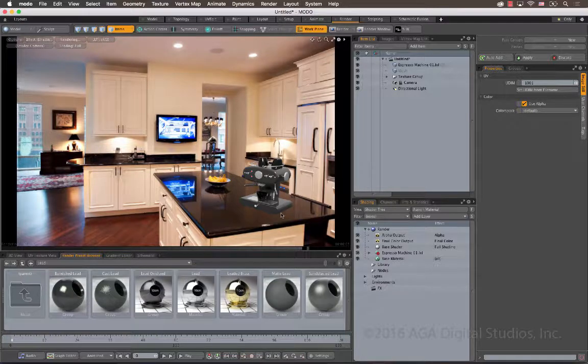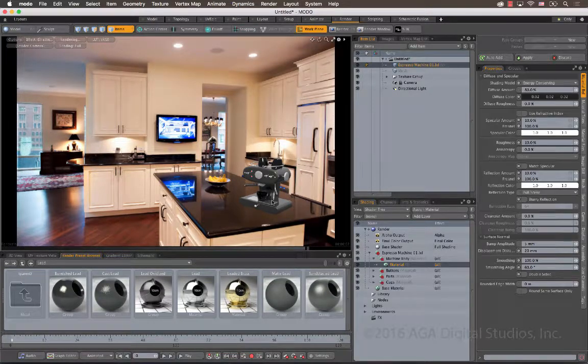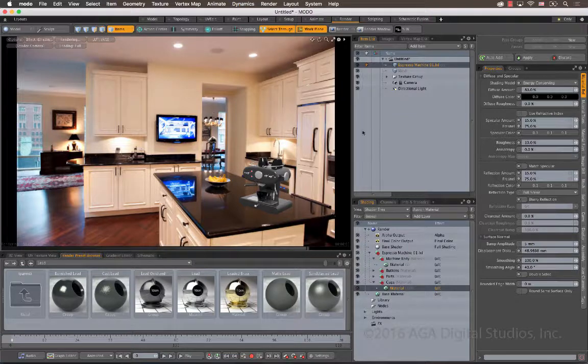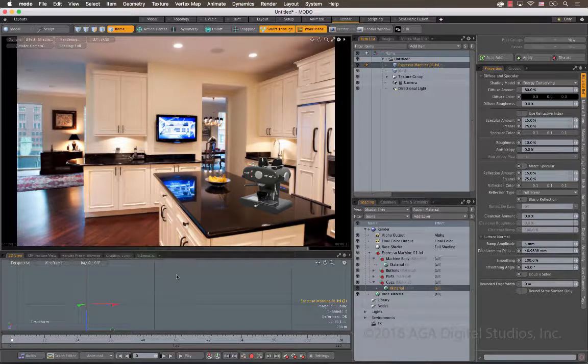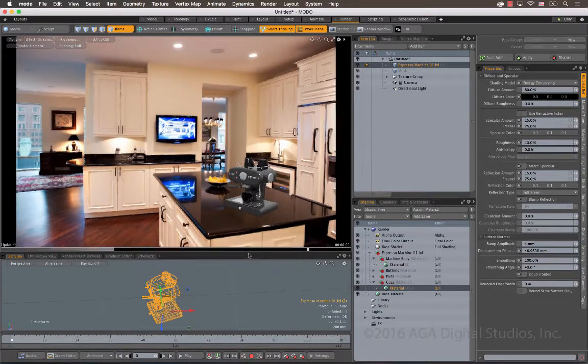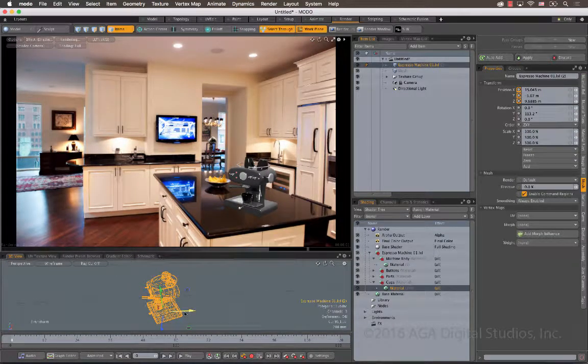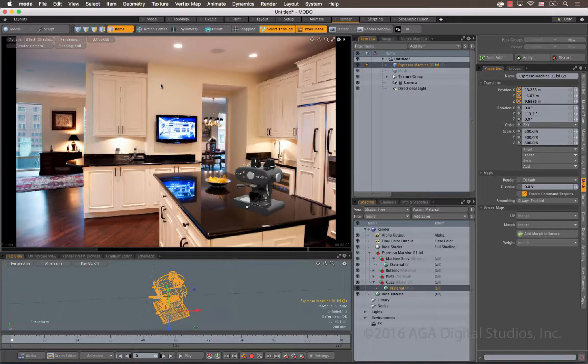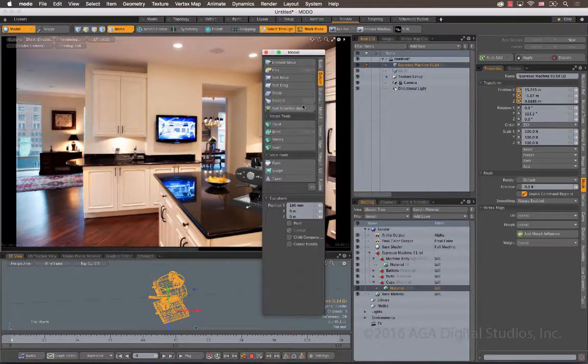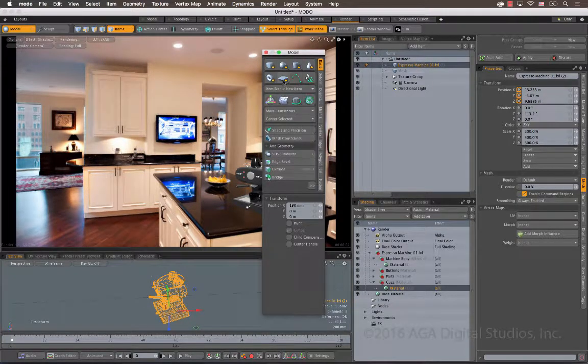All the perspective and everything matches very well. You can click in here and actually move this and still adjust it very easily. You can do it down here in a 3D view as well. But while that's great, that allows us to really place that well, it doesn't look like it's part of the scene. So there's a couple more things you need to do. Okay, so what we're going to do is we're going to come over here to Model, hold the Shift key in the Basic tab, and add a flat plane.